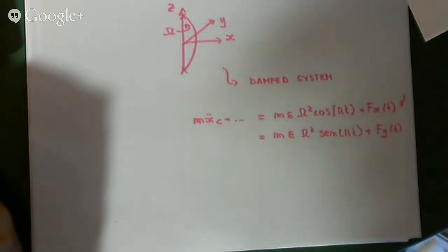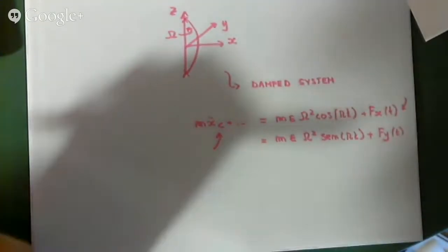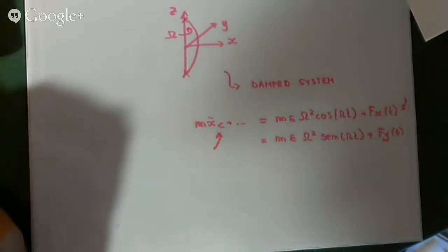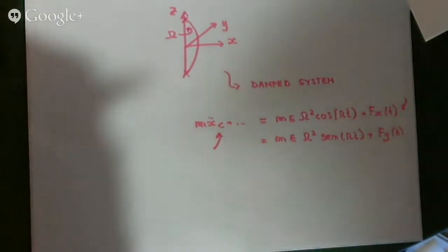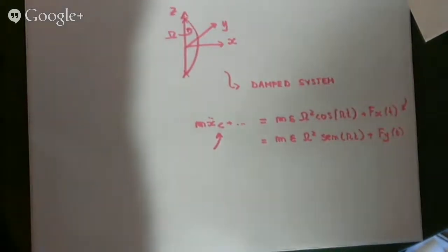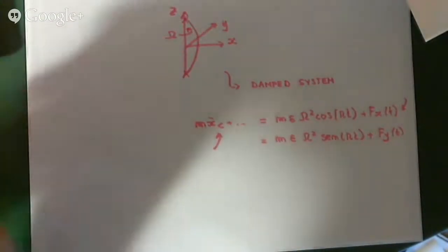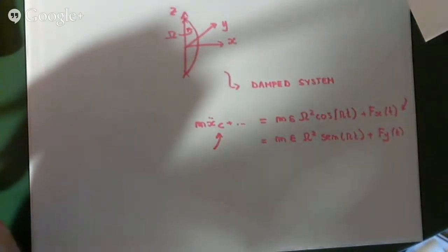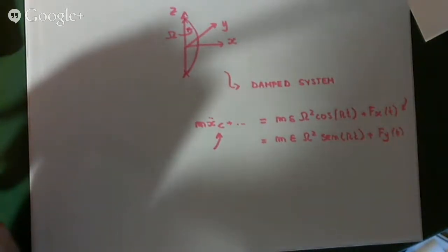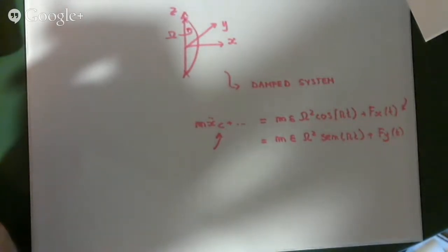Because the generalized coordinates chosen are the displacements in the x, y direction of point C, such forces are the components in the direction of the x and y axis of damping forces applied to the point mass in point C. So the force caused by viscous non-rotating damping is proportional to the speed of point C in a non-rotating reference frame.